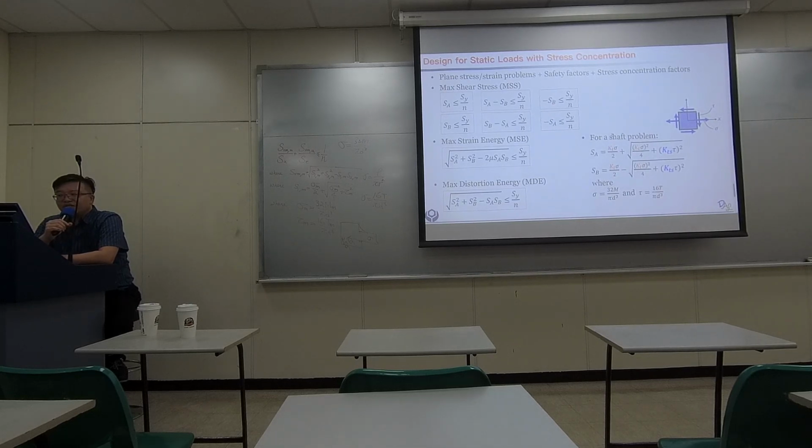But without this estimation, you will have a lower estimated stress. So in fact, in reality, when you have those notches, the stresses are greater. If you forget to consider stress concentration, you may see a greater value.